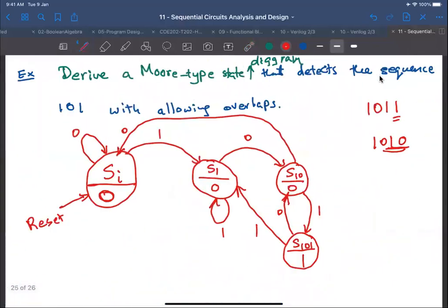Let's leave it as an exercise to you to do the state assignment and then do the 2D state table, K-maps, and then draw the logic circuit, okay? Try it for 1 or 2 assignments and just convince yourself that you'll get different hardware each time, okay? All right. Now, we covered what we call sequence detection.